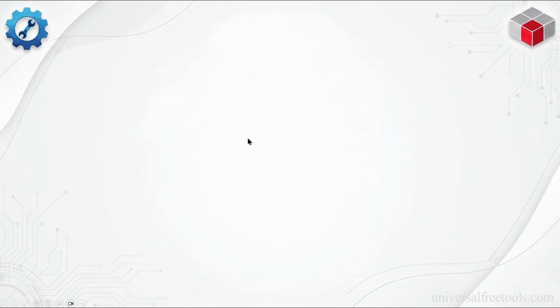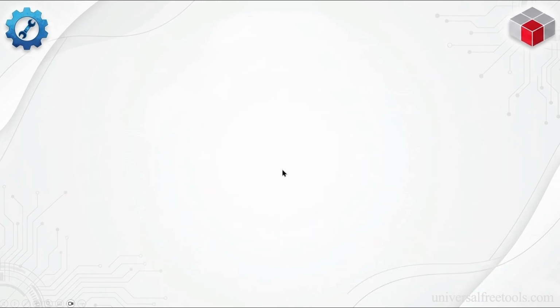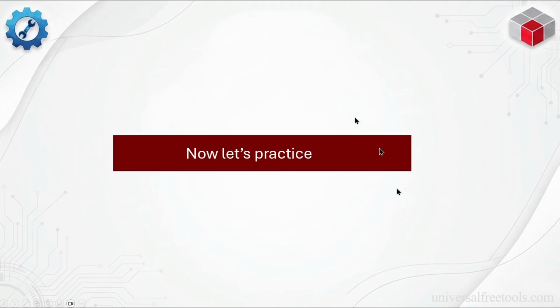Now we are on capping sequence. This sequence will wait for the bit coming from the gating sequence. When the bit reach the motor of capping station run, the cylinder move down and the motor start torquing gently the cap. The speed and torque of this motor should be not so high. The objective of this station is just to put the first 2 threads of the cap. When we reach the step 5, the motor stop and the chuck move up, and the sequence send done bit to the gating sequence to gate this bottle out and send the next bottle. You can stop the video and go back to understand the sequences.